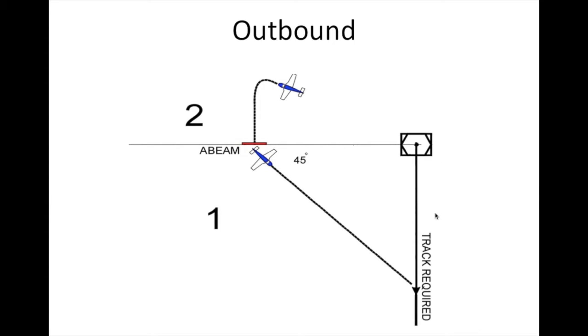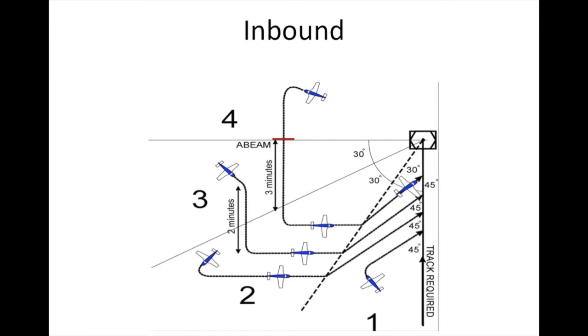Okay, now we come to the little bit more subtle, more complicated interceptions, which is intercepting inbound radials. The way it works here, let's say you've been instructed by ATC in this example to intercept radial 180 inbound. So here's the 180 inbound coming, that's the south one, and it said inbound, it's towards the VOR. This is the radial 180 coming out of the VOR south, but I need to intercept it going inbound, which means towards the VOR.